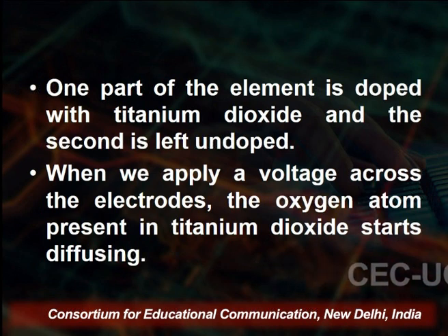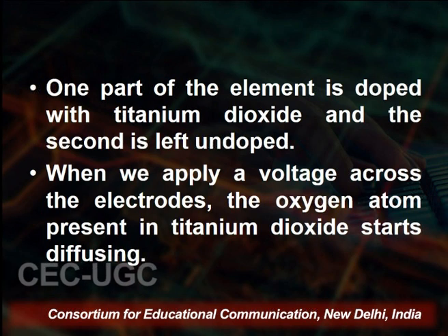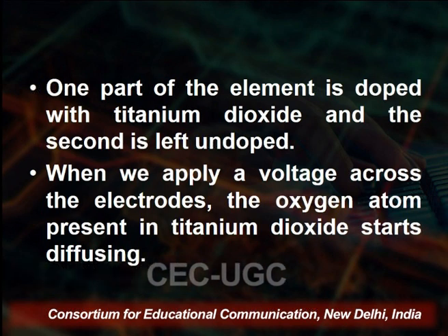So, when we apply a voltage across the electrodes, the oxygen atoms present in the titanium dioxide start diffusing, and the direction of the oxygen atom diffusion depends on the polarity of the applied voltage.